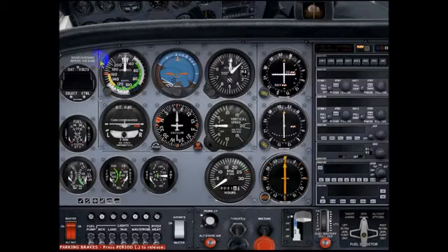Okay, so here we have our airspeed indicator. We have a red radial line here. This is marked at 160. It's calibrated at 160 knots. That is VNE, which is the never exceed speed. Maximum structural cruising speed is the top of the green arc, and this is 128.